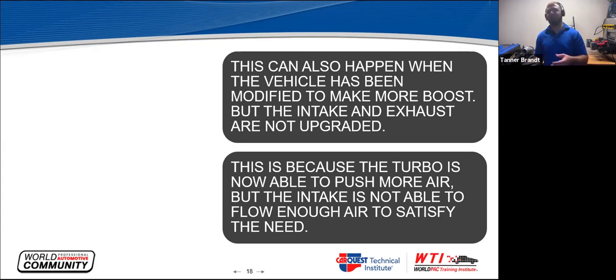I used to see this a lot on the diesel side of it. Kids would straight pipe the truck and then they wouldn't do anything to the intake side, and they would tune it. So they'd leave a stock air box, a straight pipe, and a tuner on it. It's flowing more fuel, also flowing more air out of it. And in return, now it can't bring in enough air to make up for the rest of the engine. So then you end up with a vacuum again on the intake side of it. So as you increase horsepower, increase fuel, increase air out, you need to also be able to increase the volume of air that's going to go into the turbo.